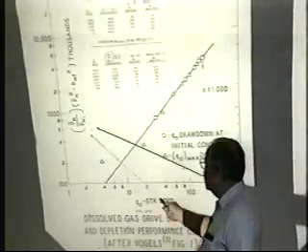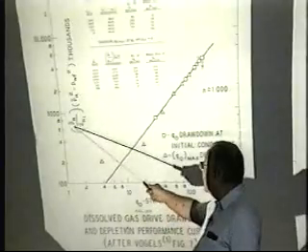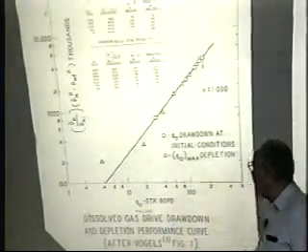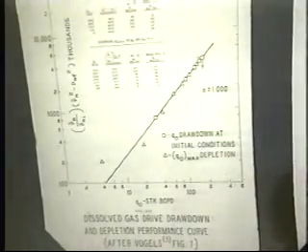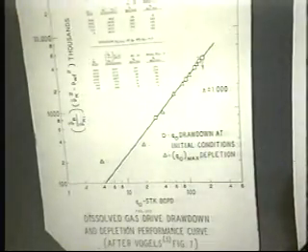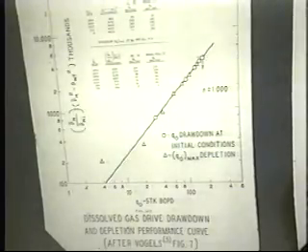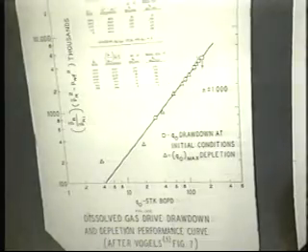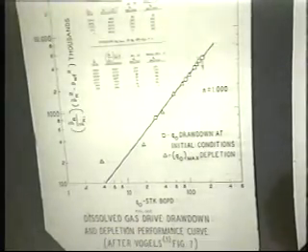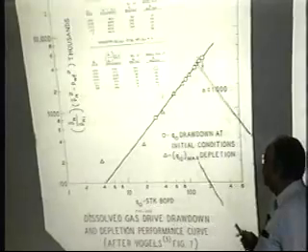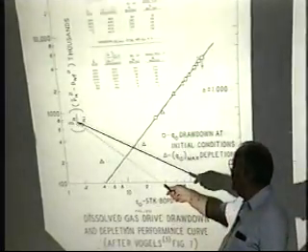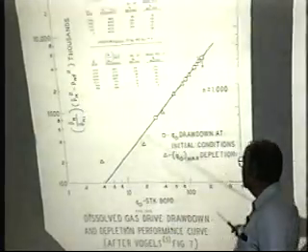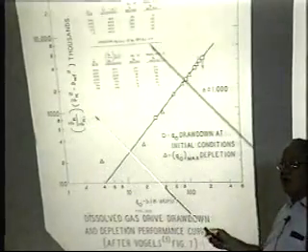You can approximate that shift with pressure depletion by multiplying the delta P squared term by the ratio of the shut-in pressure at any time to the initial shut-in pressure, above the bubble point pressure. You've got to go below the bubble point before you start building up gas saturation to get a shift due to relative permeability. If you take all of Vogel's data that he published, and even that other paper, and you use this form of equation, all of those curves that were shifted